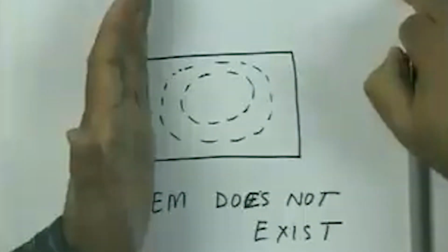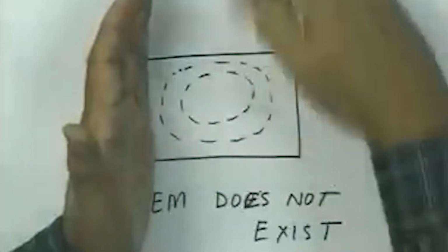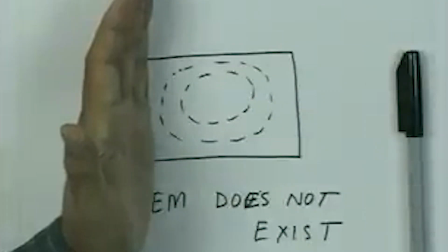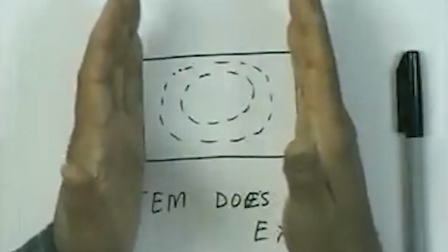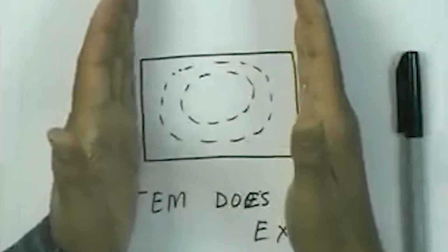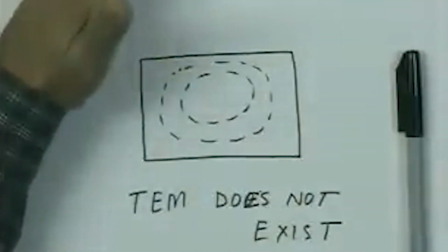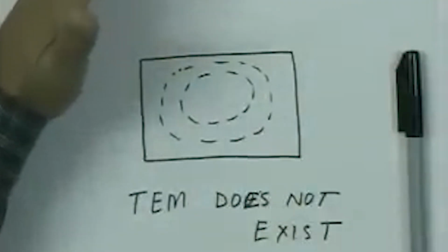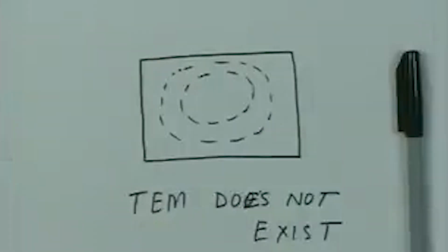Wave is going to travel in the z direction, and these two walls are pushed to infinity. So, as a limiting case of the rectangular waveguide, by pushing these two walls to infinity, I can get the fields for the parallel plane waveguide.